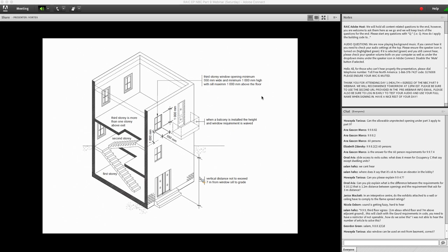So the items under Part 3 jurisdiction is just saying that even though your building is being classed as a Part 9 building, depending on what you're looking at, some items may fall under the fire protection requirements in Part 3 of the code. An example is, as we indicated, where you have a basement that has more than 1 story or exceeding 600 square meters in area. In this case, remember, in classifying the building, we classify it based on the building area and the height of the building measured above grade. So it remains a Part 9 and the basement would have to be Part 3.